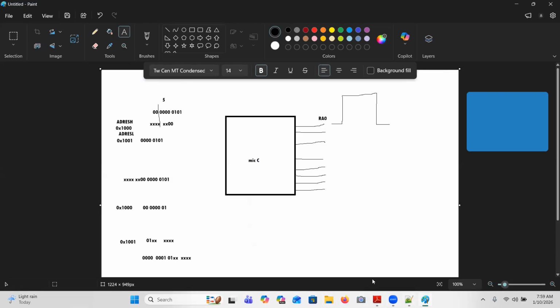This ADCON1 and ADCON0 are control registers. They have nothing to do with the result register. Here I have separate registers ADCON0 and ADCON1, which are 8-bit in size. Your ADC converted 5-volt result will not be stored in these registers. They are control registers. The results are stored in ADRESH and ADRESL, which are other independent registers.